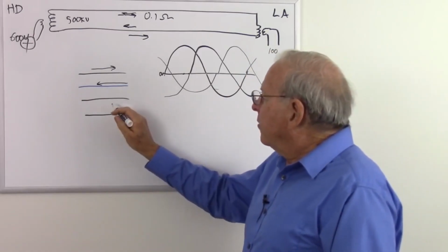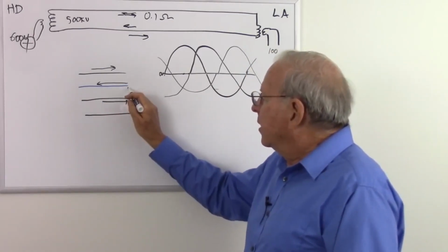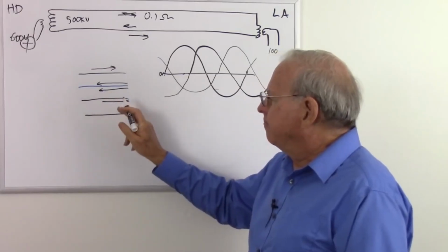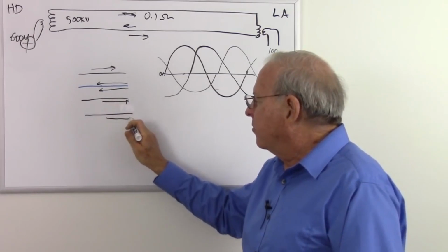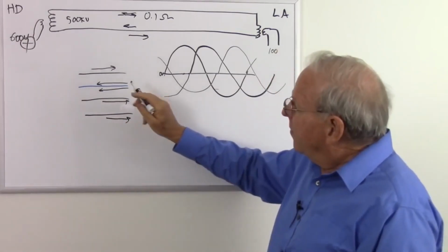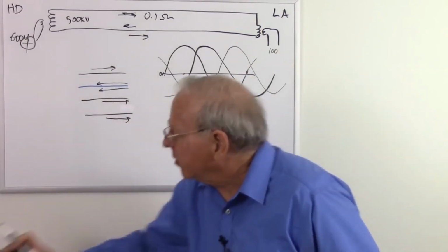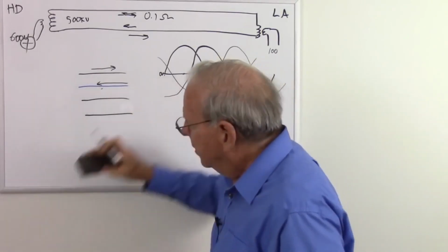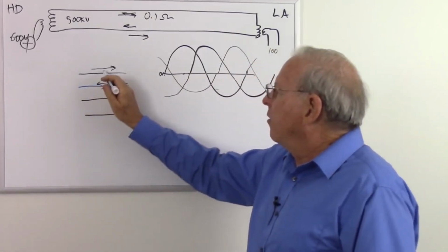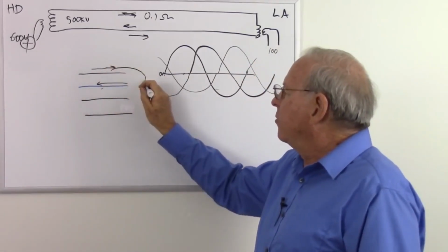And we have another time the voltage is coming up on this wire and then again returning on that wire. Now it's looking like this wire is going to have to be 3 times as big because it carries all 3 phases, right? Well, what's actually happening, if we look more closely, at one moment in time, this wire is carrying current this way and then returning that way.